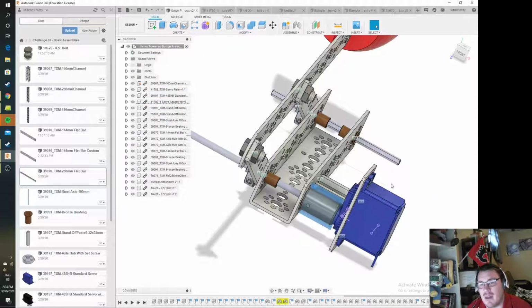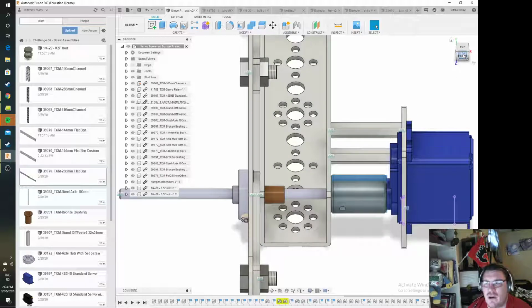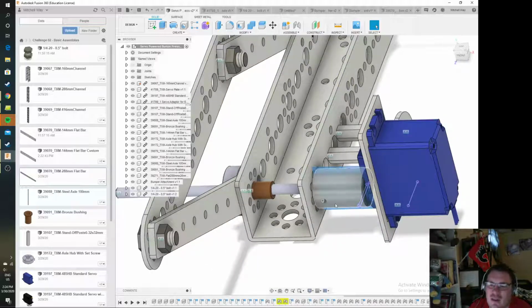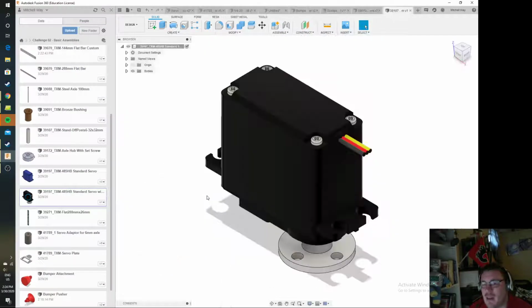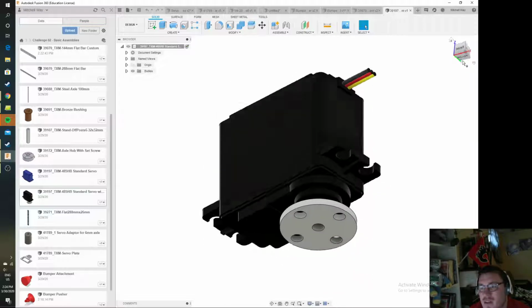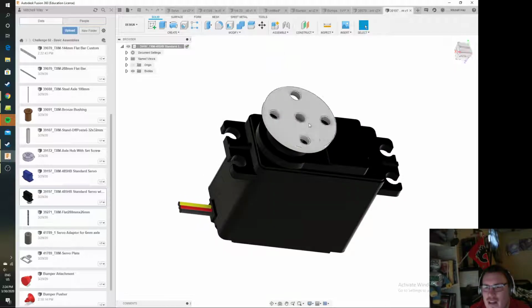Okay, so if you look at this, there's something very noteworthy. A lot of students I see in robotics do something that I don't necessarily agree with. They'll actually go in and take their servo, their standard servo itself, and what they will do, clearly this one imported upside down, such as life, and what they will do is they will actually attach their mechanism directly to the servo horn. And yes, that's the terminology, this is your servo horn, okay?